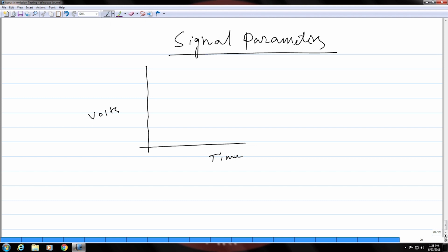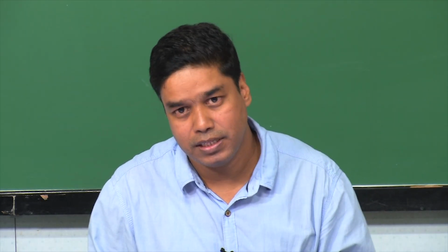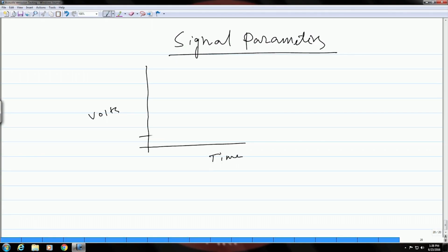Okay. So, when you do acoustic emission testing, the first thing that you need to do is define a threshold, and anything above this threshold is taken as a real acoustic emission signal, and below this threshold it is considered noise. Okay. So, you may find signals like this, some may be below the threshold, then suddenly it might go up.